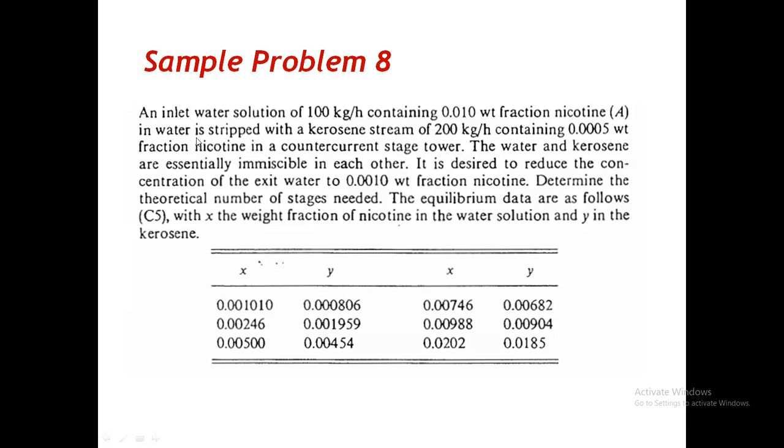Notice the term that was used. This is a process of stripping because you are taking your solute from a liquid phase. Although in the case of stripping or desorption, as opposed to gas absorption, the phase that takes out the solute from a liquid phase is the gas phase.